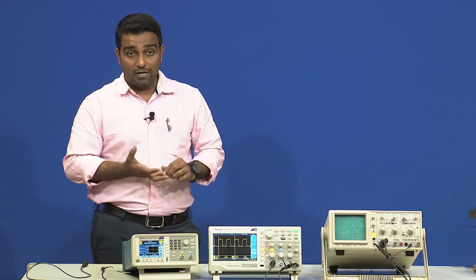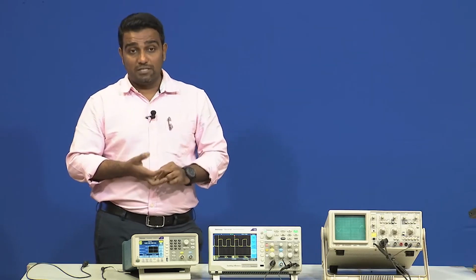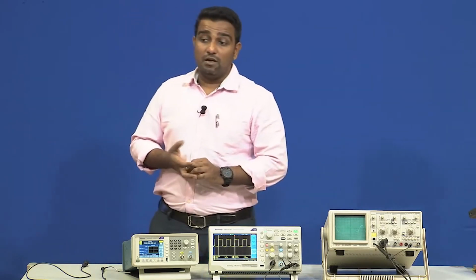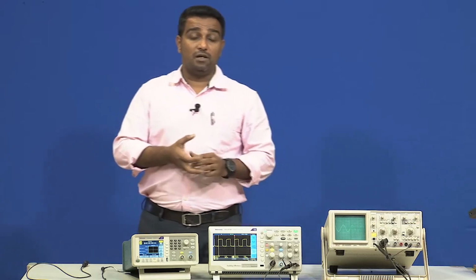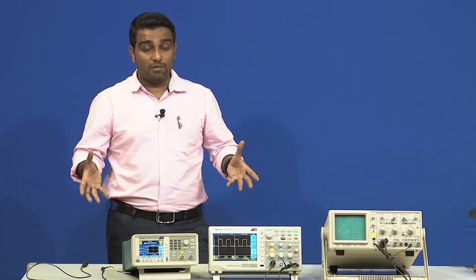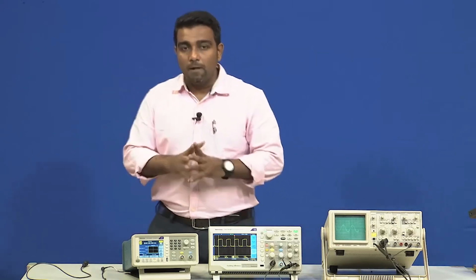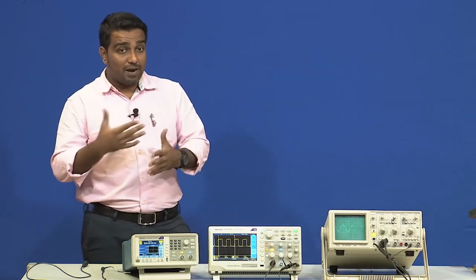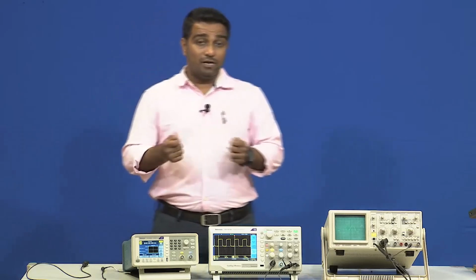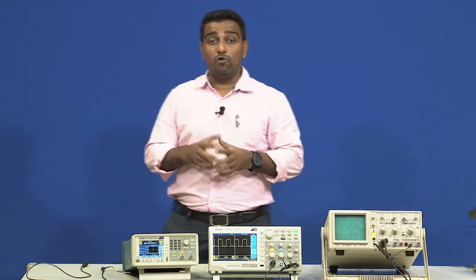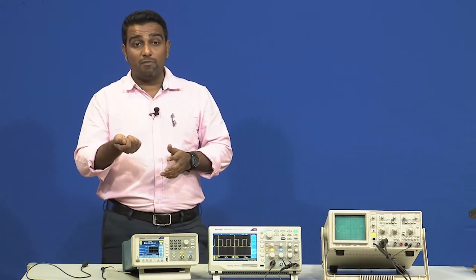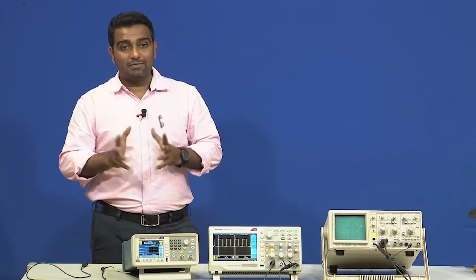We have measured the AC voltage, we have measured the DC voltage, and then we have understood the DC power supply. One was an old version, one was a new version. In the newer version there was plus minus 15 volts, you can change the voltage, you can change the current. I told you that if you do not know, always keep the current on maximum, probe on maximum.